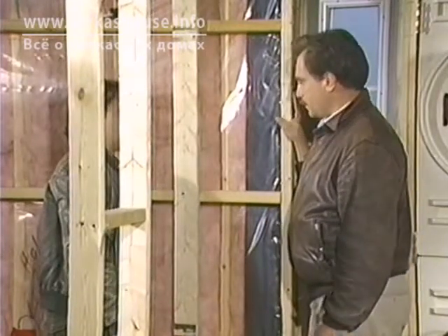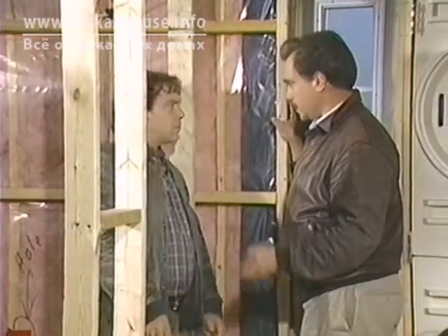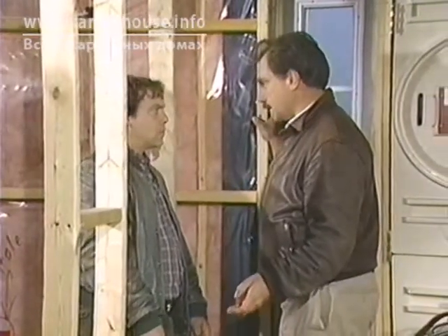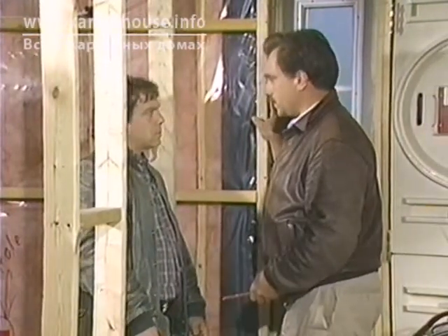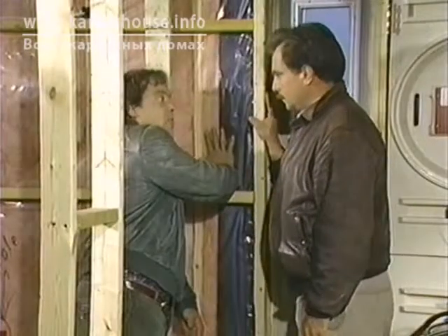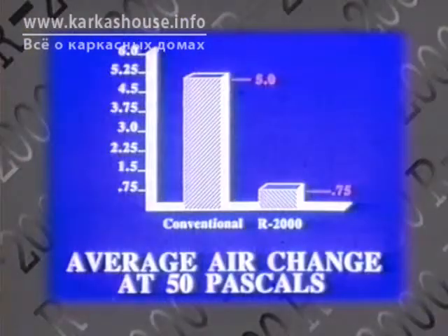The electricals have been very carefully taken care of at each electrical box. The plumbing stack has been sealed. All the places where we previously saw difficulty, we now don't have any. So this is the famous continuous air vapor barrier. The fact that it is continuous and that there's no air leakage is the root of lower fuel bills and good air quality and all of those things? Well, it's the beginning of all of those things for sure, but perhaps most importantly within the context of a wall section, it prevents the movement of water vapor into the walls, and that's really the key issue.